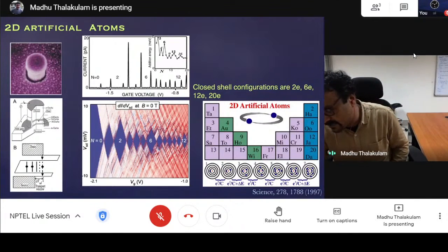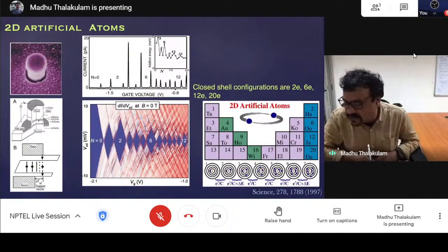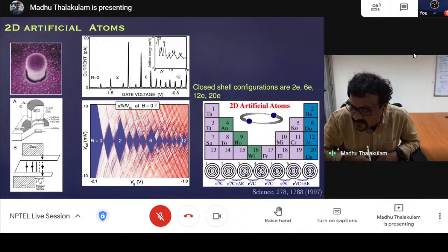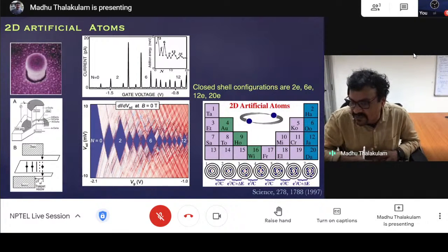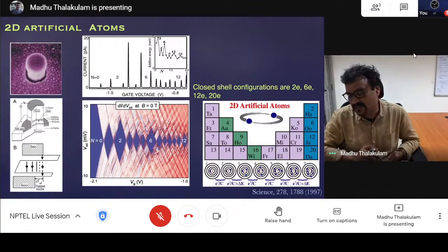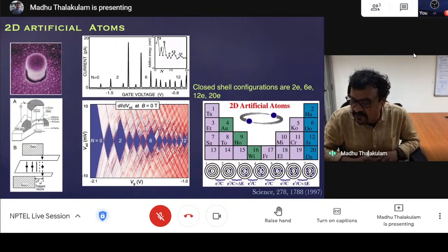So, Coulomb blockade is applicable for any kind of charge transfer, but of course, you also need a system to confine this. It is just an electrostatic effect, plus you also have the condensation of the charge. Usually Coulomb blockade is observed for electrons and holes, very routine. Both you can observe, but those are the only reports that I'm aware of. But in principle, it's not a quantum mechanical effect. It's a classical effect. So these large quantum dots are generally called classical dots also.